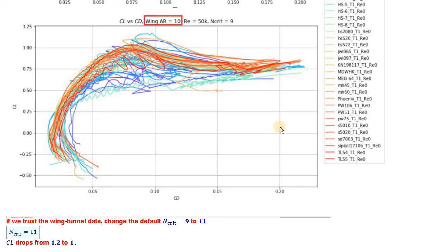From the previous section, you have seen that the maximum drag allowed for this motor is 0.6. In this case, it is 0.2, so it's not a limiting factor at all. So you just pick the maximum point for each curve to get the maximum lift coefficient at low speed. If the motor is not as powerful, we have less thrust, then we might have the maximum drag coefficient somewhere here or somewhere there. Depends on the situation. In that case, you would have to pick the maximum position in this range, below the maximum drag coefficient limit.